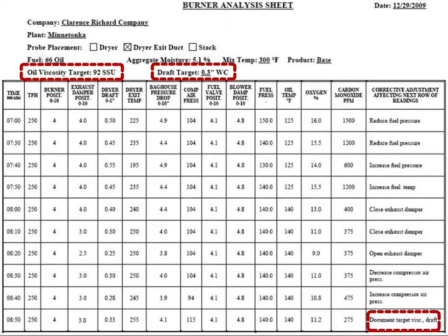We had a choice to adjust the fuel or air or other variables that affect combustion. We chose adjusting the fuel pressure first. Some adjustments are hard to make, so we normally save them till last if they in fact need adjusting. It is easier to adjust fuel pressure, exhaust damper, compressed air pressure, fuel temperature, spin vane settings than adjusting combustion flights, air-fuel valve linkage, flame holders, etc.